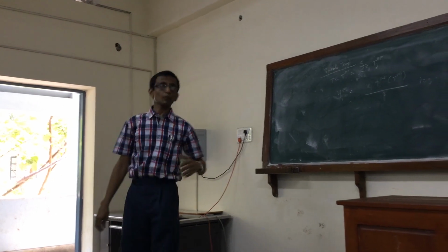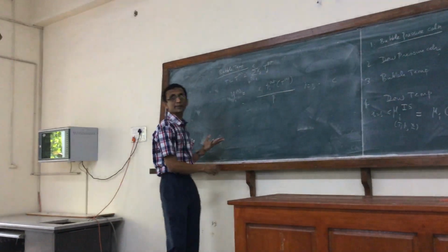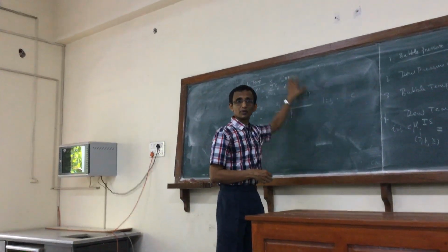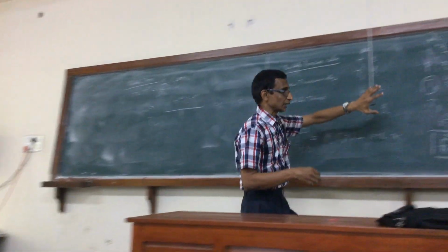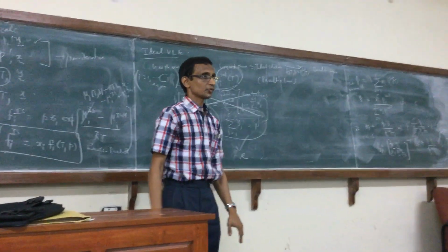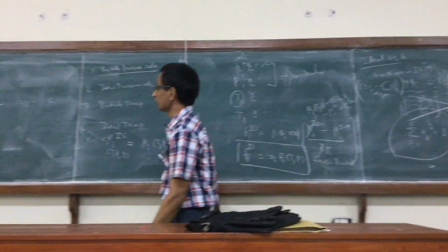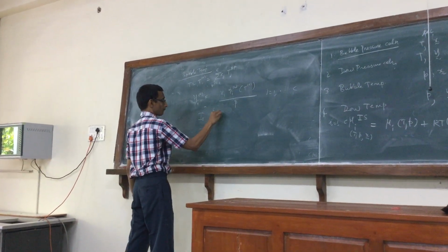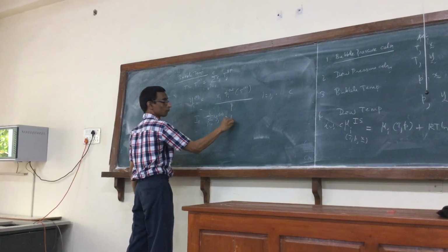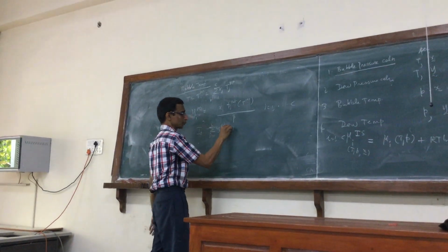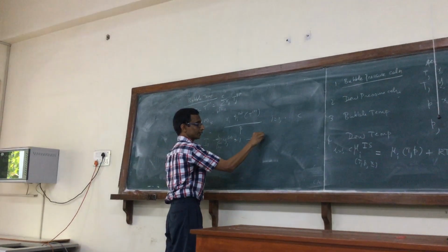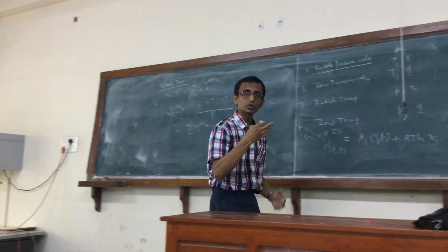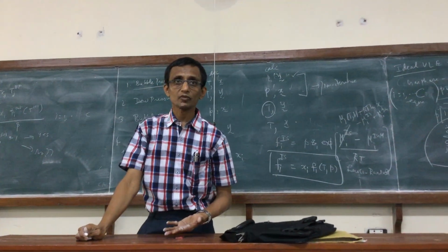Right? So one algorithm would be to check whether the values are tight here. Because I have satisfied now these equations for this temperature. But there is one equation left which we don't know. So let's verify whether the sum of yi is approximately 1, that means you have to set a tolerance. If yes, then I can stop. If no, then what to do? So how to choose the next temperature?